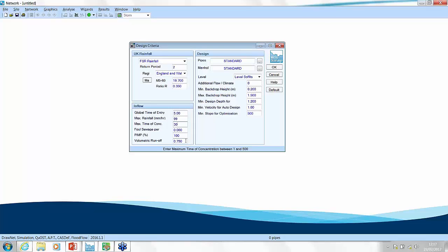And as I said, there is a lot of debate about whether this value should be increased, particularly in catchments that have a sort of clay soil where you might expect permeable areas to provide a contribution. So again, this is a discussion that should be had when it comes to setting these standards and on an individual catchment basis, depending on where you are in the country.